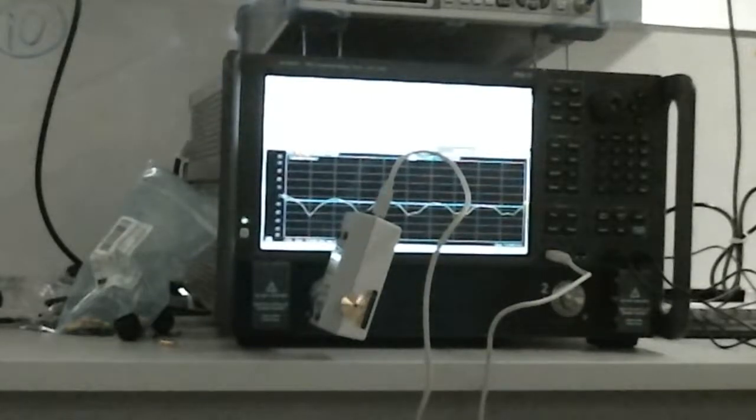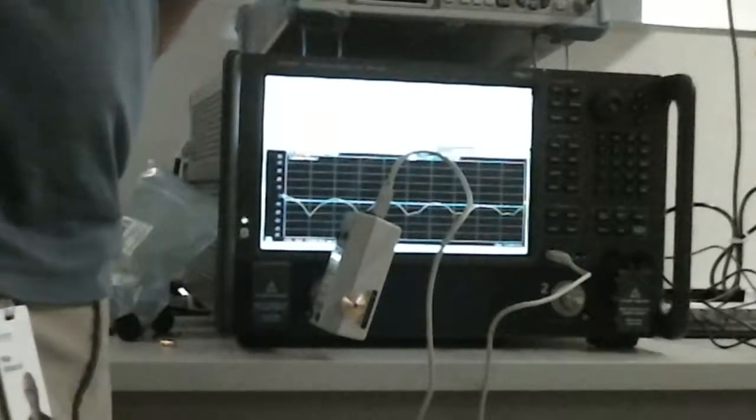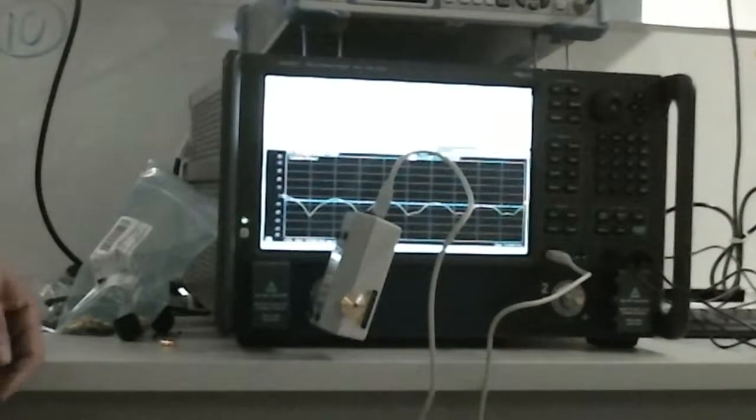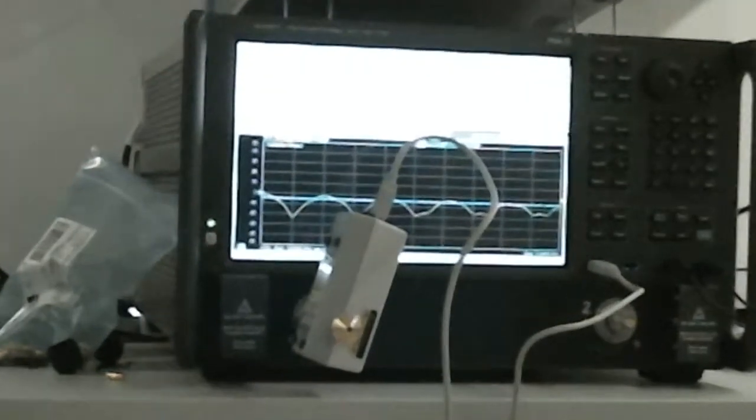The only other thing I want to talk to you guys about is this. Have you used a torque wrench before? If you're typically used to using BNC connectors, BNC just plug into each other and you're done, right? There's nothing really complicated about that. With the SMA and the higher frequency connectors, there's a specified torque, and this is basically so that the pin depth when you make a male-female connection is always repeatable.